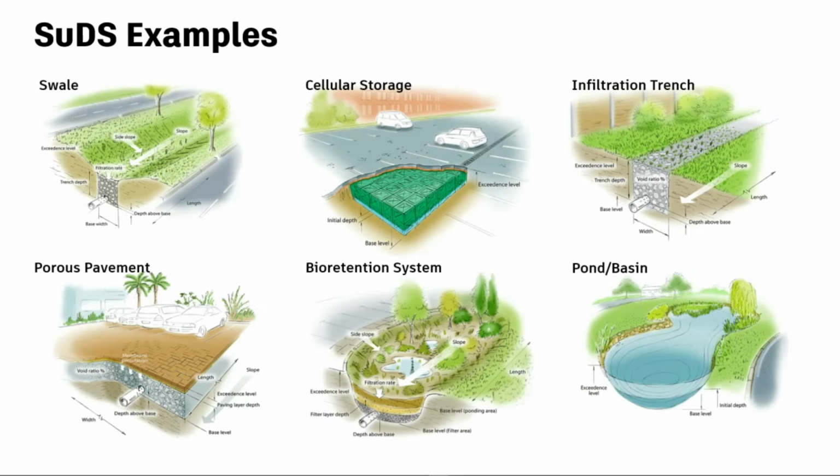Sustainable drainage structures tend to differ in shape and size, but more or less have a similar objective in attenuating stormwater runoff by mimicking natural drainage patterns. The names of these structures can also vary too. For example, a bioretention could also be called a rain garden or a tree pit. So take a moment to explore these examples in combination with real images to get a feel for how these structures are formed in reality.